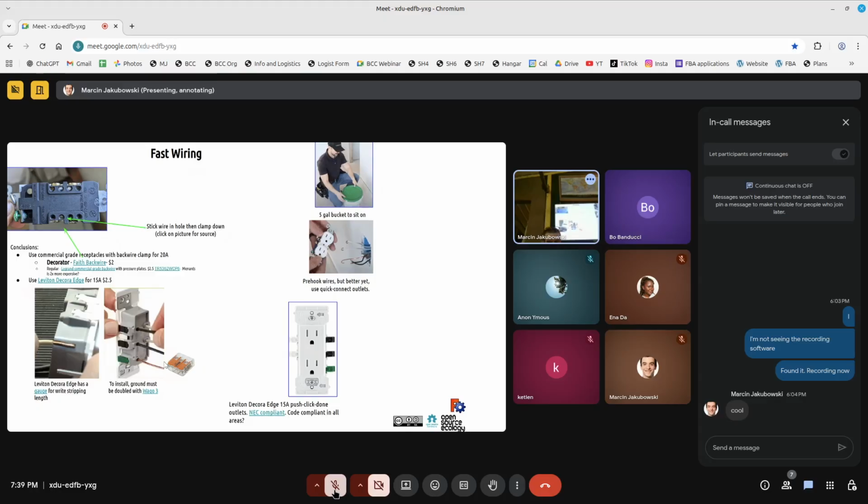Do you have the geothermal cooling? Did y'all actually install that? We did not install the geothermal yet. So in this workshop, what we can do, I mean, it's kind of nasty out there, but that means laying out, in the simplest experiment, just simple 1-inch polyethylene pipe. 1,000 feet of that gets you about 10 to 20,000 BTU of thermal energy, like a heat pump. Yeah. About 1,000 feet of 1 inch can get so much cooling.